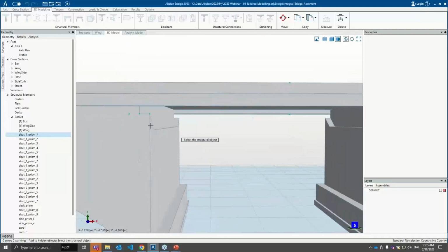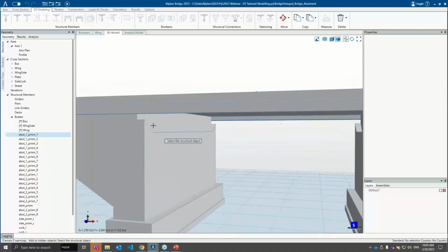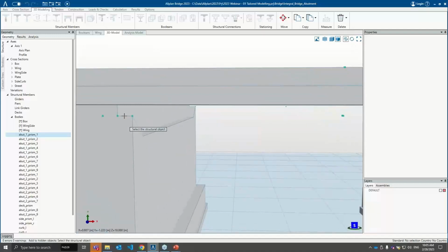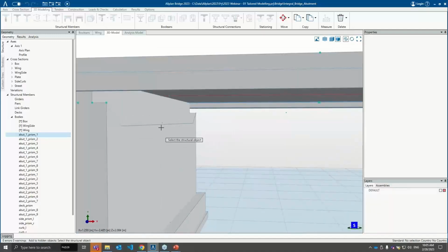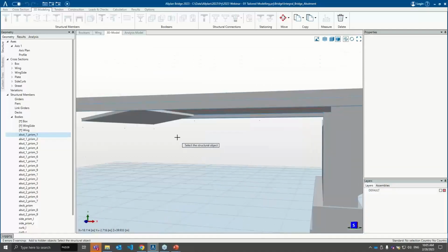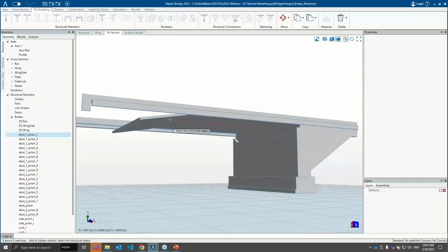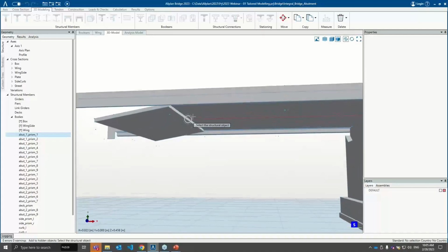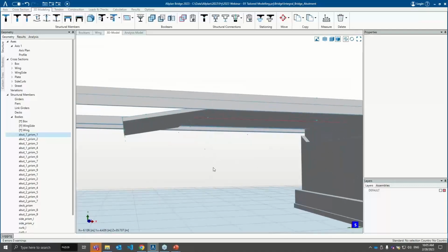What we did was, we had an abutment wall, and from the abutment wall we subtracted the deck prism, which gives us this subtracted object. When we hide this, you can also see the wing wall, or the approach slab, placed at the top, which is not touching or aligning with the abutment.